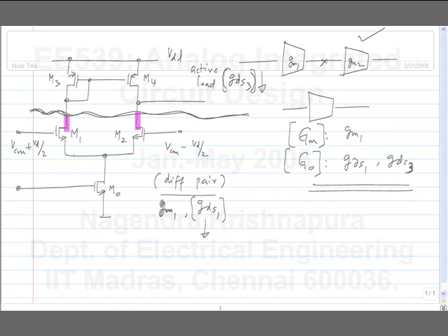Can we not degenerate with the resistance? Okay, that's a good question. So the suggestion is I will degenerate with resistance. So what will happen now? First of all, what changes now? I had originally GM1 by GDS1 plus GDS3. So how will this expression change? And what else?